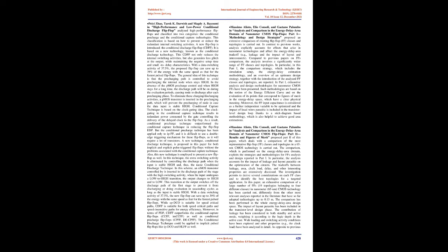Conditional capture technique is based on the clock gating idea. The clock gating in the conditional capture technique results in redundant power consumed by the gate controlling the delivery of the delayed clock to the flip-flop. As a result, the conditional precharge technique outperformed the conditional capture technique in reducing the flip-flop EDP. But the conditional precharge technique has been applied only to IPFF, and it is difficult to use a double-edge triggering mechanism for these flip-flops, as it will require a lot of transistors.